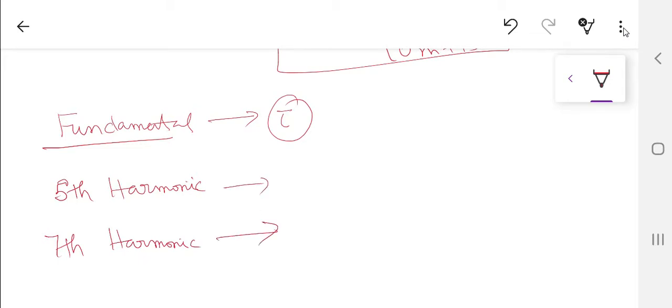These are the first harmonics which come into play at present. The fifth harmonic is going to produce a torque tau 5, which is opposite to the main torque. This is produced because of the stator revolving field, which has the fifth harmonic, and then it induces an EMF inside the rotor that is also a fifth harmonic, going opposite. Those two fields interact with each other and give rise to harmonic induction torques. And the seventh harmonic is going to be almost in the same direction.